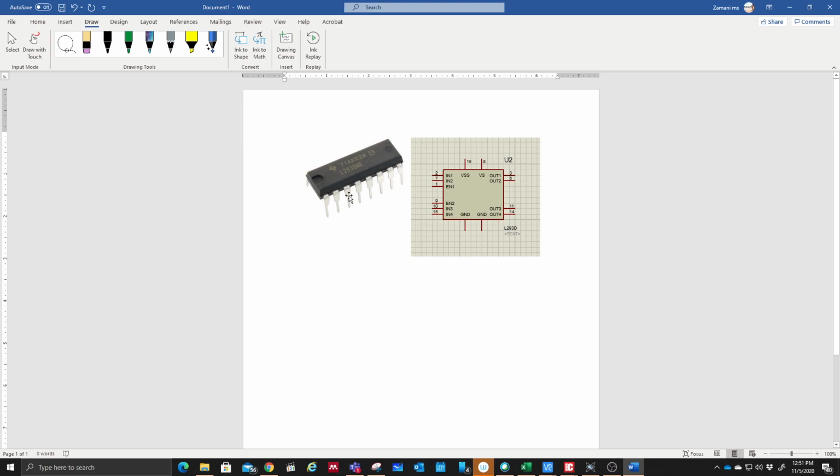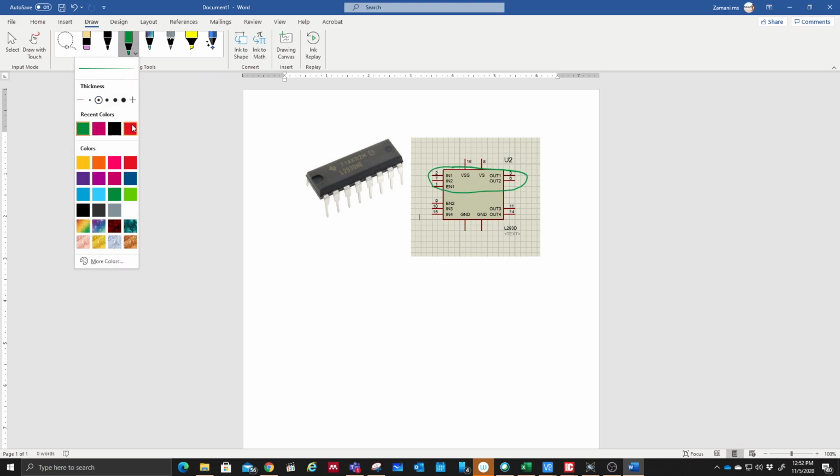So you have to read all these pins. Which one is which pin? For example, this is pin 9. So you have to read which one is pin 9. You start from here because of this symbol, 1, 2, 3, 4, 5, 6, 7, 8, 9, 10, 11, up to the data sheet. Over here, you look carefully. This driver can drive two motors at the same time. This is the first one, and the other one is this one.